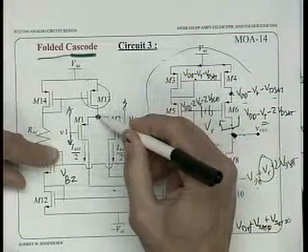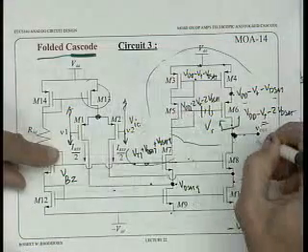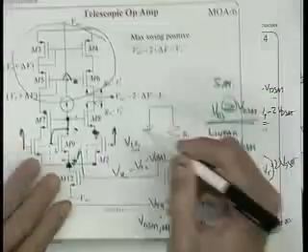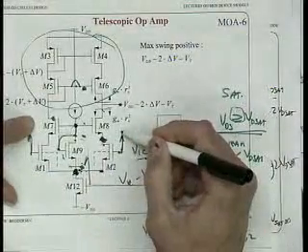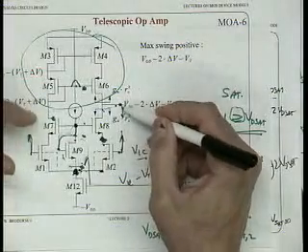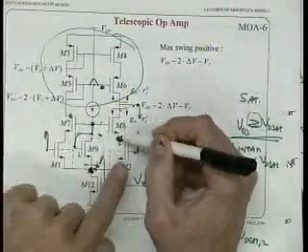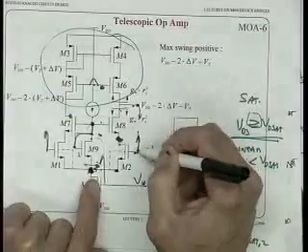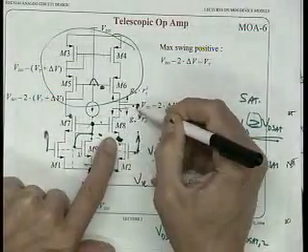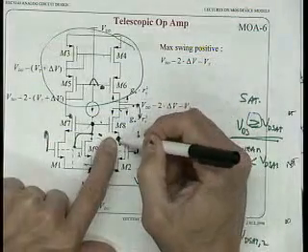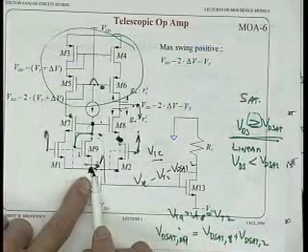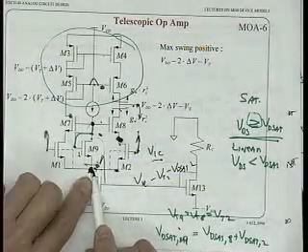How does that affect our output swing? That's the issue here, right? When this common mode voltage went up, our output swing was damaged because when this went up, this voltage went up, that meant this voltage went up, so our output swing was limited by what the voltage was here, and that's a function of this voltage down here at the source of M2.